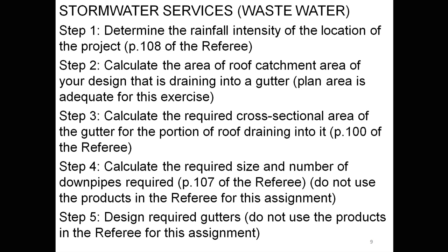Overflow. Are there any spigot requirements or some kind of an overflow point? Yes. Generally, between the gutter and the downpipe, you do a sump, which is essentially a deeper portion of the gutter, where water can collect if necessary, and then that sump generally has an overflow, which then goes to the outside.